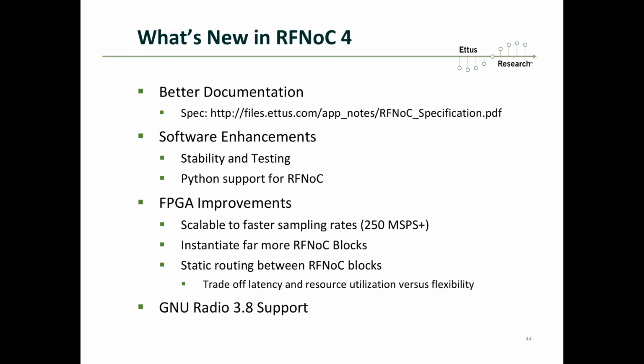It also provides a new static routing capability that enables users to better trade off latency and resource utilization against flexibility, in terms of using static routing versus dynamic routing between blocks. And RFNoC 4 now supports GNU Radio 3.8, which is the most recent release of GNU Radio.